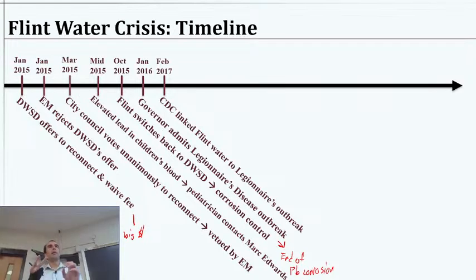And then there's another aspect of just that big of a change of water chemistry in the pipes. And the fact that, again, kind of looking all the way back, we don't have many people living here compared to what the infrastructure was designed for. There's actually a lot of empty homes and dead zones in the distribution system.